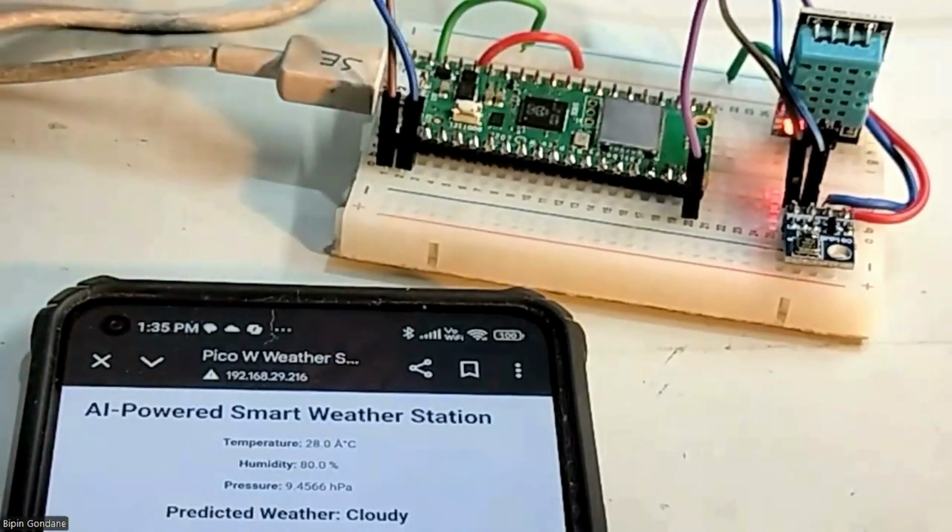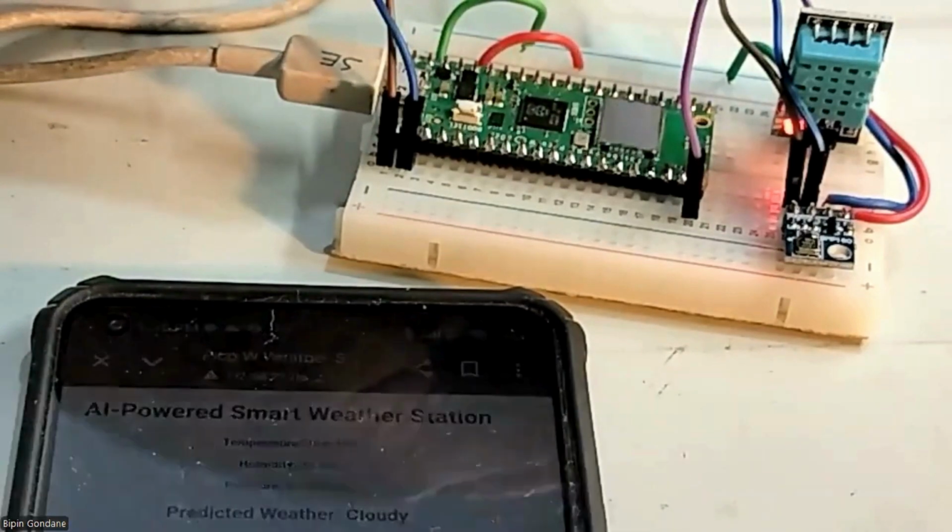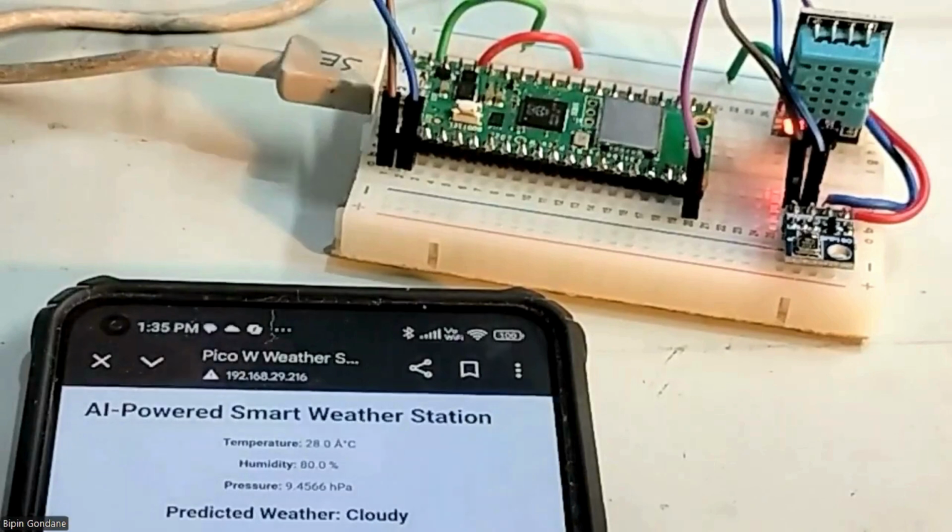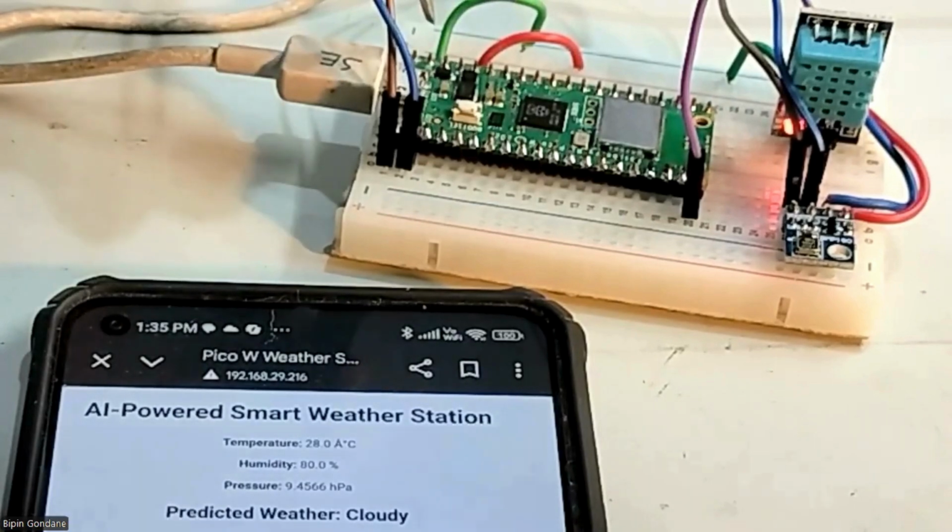So this is going to your DHT sensor, here I have used the DHT11 sensor. Please remember that, okay? Both of them are working with 5 volts, which I have taken from the board. This is the 5-volt jumper, which is from pin number 5, right? On the right-hand side, all 5 pins are related to power. Pin number 3 is ground, which is connected to ground.